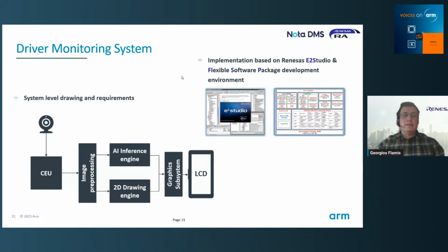Then we have the drawing engine and the graphics subsystem, which includes the graphics controller driving the LCD over an 8, 16, 18 or 24-bit RGB LCD interface. A very important part is the 2D drawing engine for raster and vector graphics. That engine provides flexible functions that can support almost any object geometry and allows creating bounding boxes, triangles and lines to help the final application.